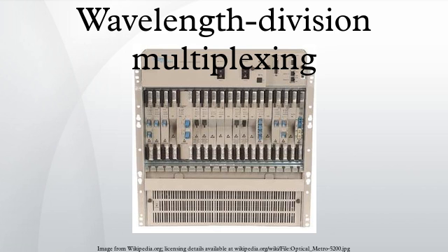2R, retime and retransmit. Transponders of this type were not very common and utilized a quasi-digital Schmitt triggering method for signal cleanup. Some rudimentary signal quality monitoring was done by such transmitters that basically looked at analog parameters. 3R, retime, retransmit, reshape. 3R transponders were fully digital and normally able to view SONET/SDH section layer overhead bytes such as A1 and A2 to determine signal quality health.